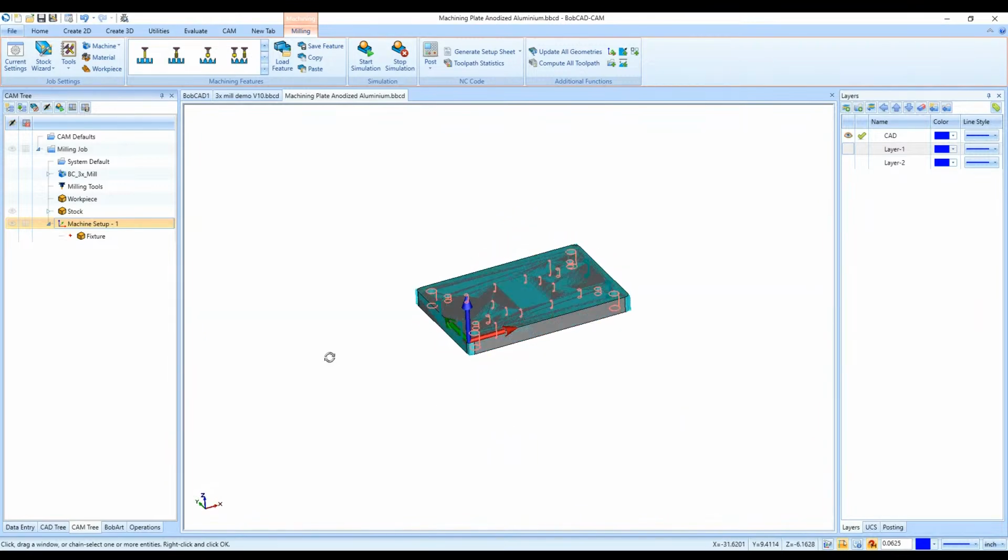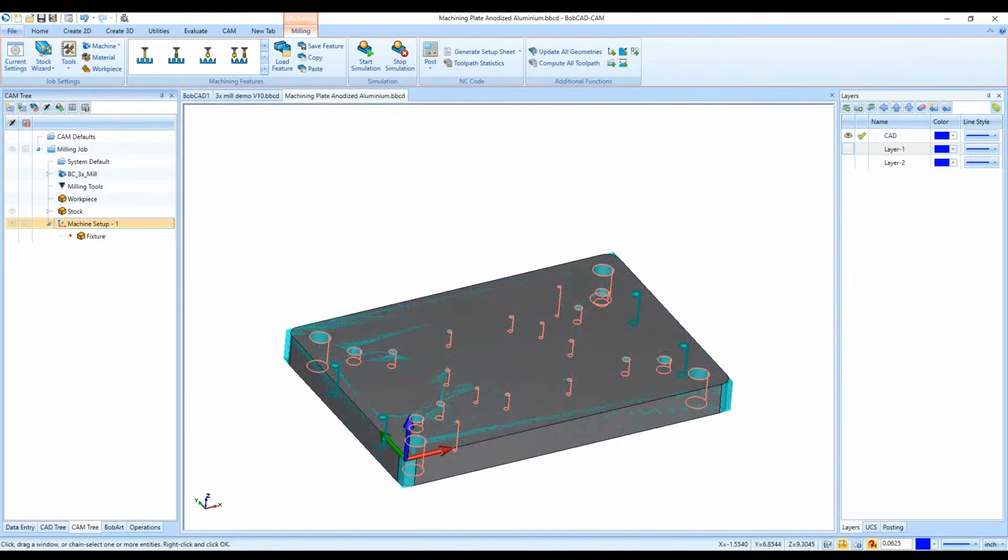So no, everything looks good here. If I scroll up or down, again, highlight each hole, and then there's a couple check boxes here, and then a drop down here. So I actually spoke too soon with defining the different hole types with a blind hole. That was already checked here with this checkbox that it is a blind hole and not a through hole for these here.